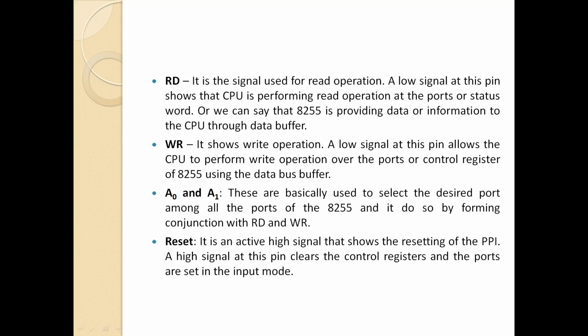There is a read pin. It is a signal used for the read operation. A low signal at this pin shows that the CPU is performing a read operation at the ports or status word. Or we can say that the 8255 is providing data or information to the CPU from the data buffer.